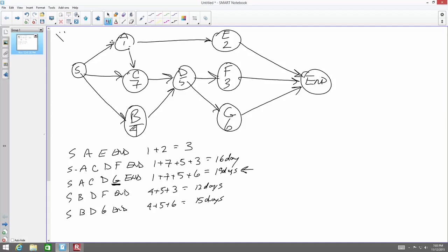As a responsible person over the whole project, whoever is intimately familiar with the design can stamp the drawing. So the structural guy who's intimately familiar with that design as it grew up through the design process is the only one that can stamp those drawings. You have to be very familiar with what you're stamping. Somebody giving me something, saying, hey, can you review this for a couple hours and stamp it? It's not a legal methodology for stamping something.